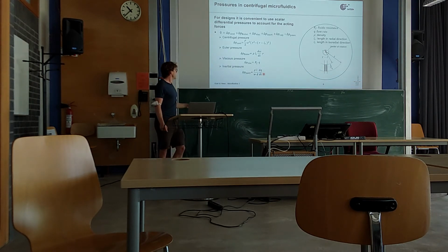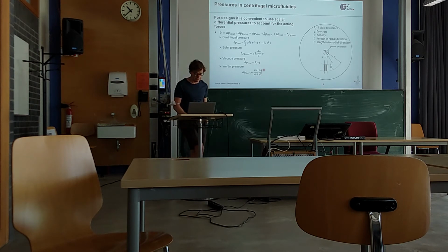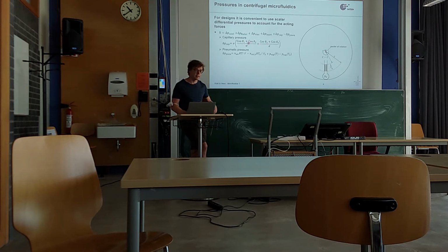So then you have the inertial pressure, which comes from the change in the flow rate. And you have capillary pressure, which comes from your dimensions of the channel and obviously the interaction between liquid and solid. So it's based once again on the surface tension and the contact angle, because you have a three-phase system consisting of the cartridge material, the liquid, and the air. And finally, that's what I mentioned before, the pneumatic pressure.